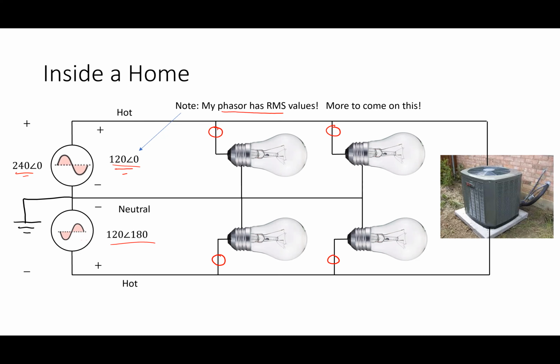And so we typically put loads that need a lot of power on the 240. Because if we put them on the 120, it would take a lot of current to give the same amount of power. There's very few things there. One would be the air conditioner, like I've drawn here. What else gets the 240? Fridge does not. Dryers, dryers are the big one. Washing machine typically not. The dryer typically does, because the dryer has a lot of power going into it.